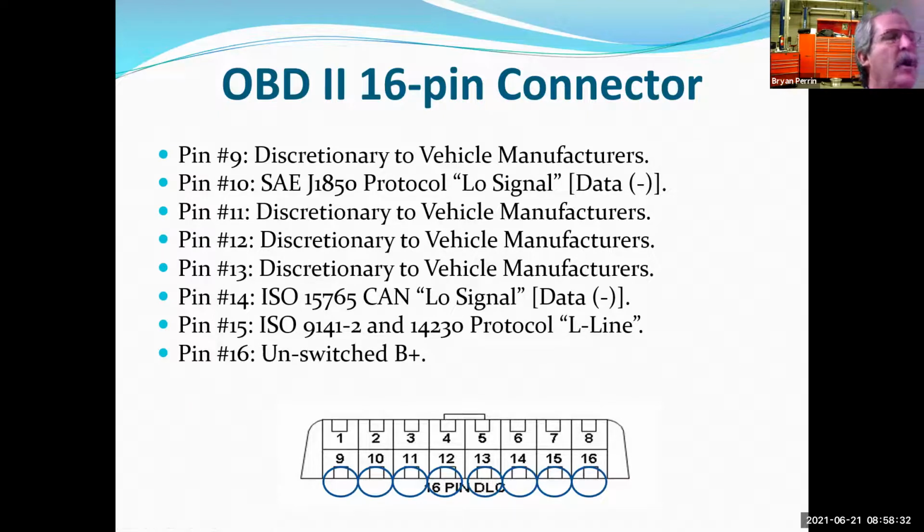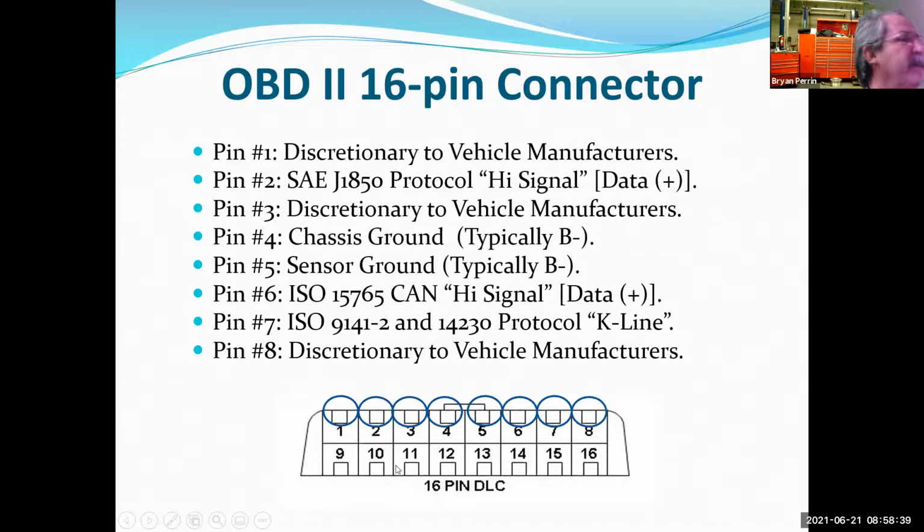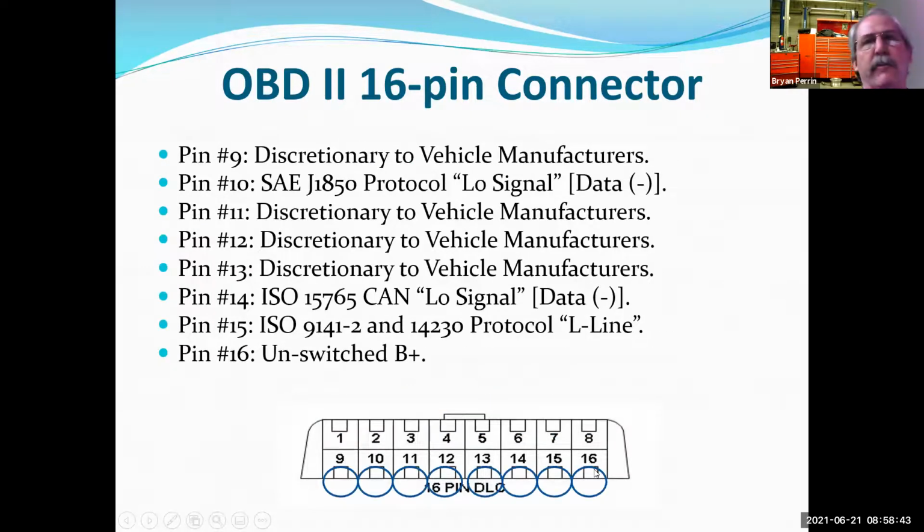So the only ones on here that I expect you to remember are 4 and 5, that is my chassis ground and sensor ground, and pin 16, which is battery power. Those are the only 3 I expect you to know.